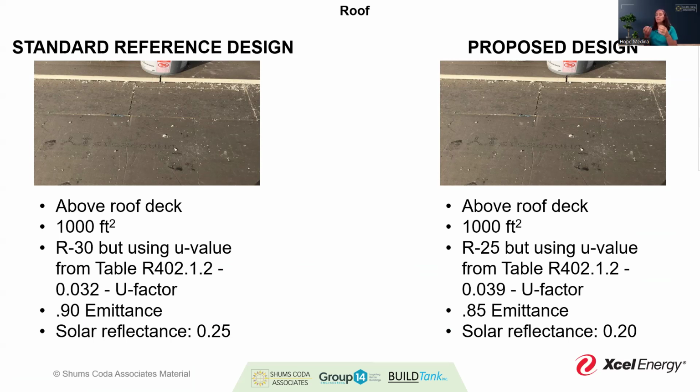All those values, because they're a deficit of what the standard reference design is, mean your roof is kind of at a negative, but maybe your walls or your mechanical equipment are at a positive. And so throughout, you're trading things off that go beyond just the thermal envelope. A lot of times people think I'm just trading within the thermal envelope and then just within the mechanical. In this pathway, you have the ability to expand on what you're quote unquote trading.